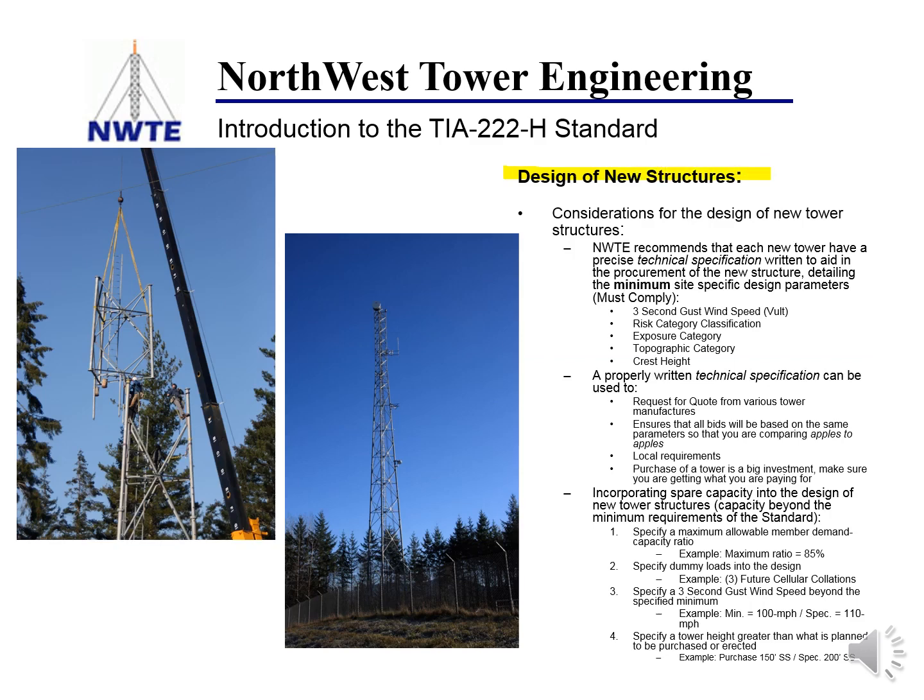Design of new towers. Right now we are going with the most onerous condition when we're designing these towers, which would be to continue using the G standard. As you can see from our earlier discussions, there's a lot that goes into specifying a new tower. You have to make sure you have the right wind speeds, all the correct risk categories and exposure categories, distance from top of hill.